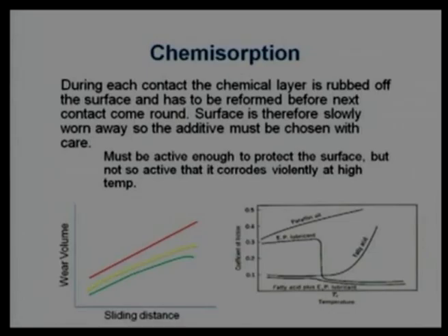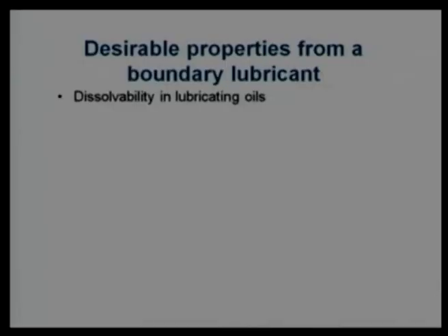So whatever the transient case, if the temperature is going very high, EP additives can react. Otherwise, they will remain silent, they will not work, even though the cost is increasing by delta. But overall we need a good result, and there are always uncertainties in machines. So if the local temperature is going beyond a certain temperature, then the EP additive should work.